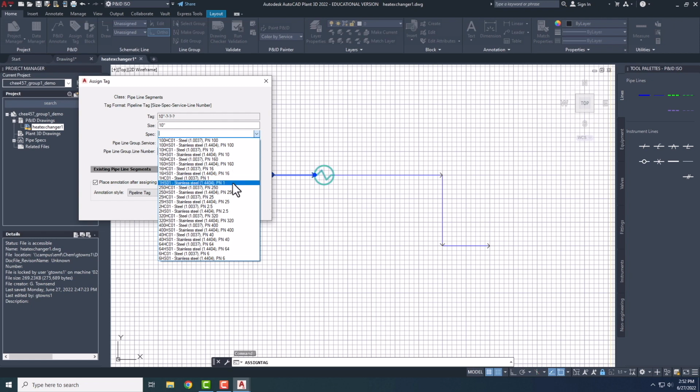You can create custom specs. I'm not going to get into it, but if you have some funky pipes that you really need and your design leader is real adamant about it, you can create your own custom specs. You'll just need to look up that on the internet. The PN is your nominal pressure, the pressure the pipes are meant to withstand. We'll say it's going to be stainless steel or even carbon steel, and it'll need to withstand 10 bars of pressure.